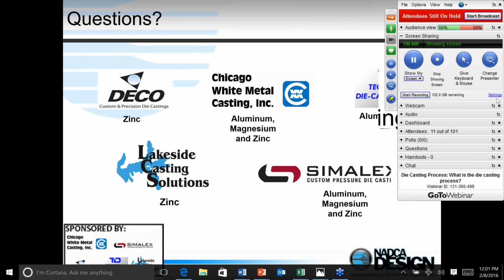But of course, production costs with die casting are so low compared to other casting processes. Die casting is generally the lowest, for example, in aluminum. I would assume a chair would be aluminum. Generally, aluminum die casting is the lowest cost way to produce a complex 3D shape, such as a chair base, for a minimum of 500 units to 1,000 units.